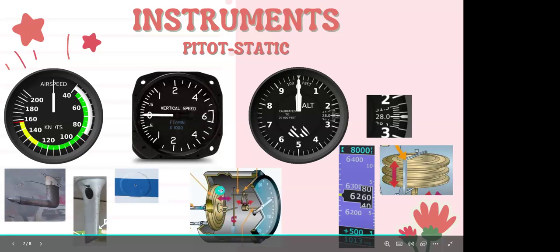Inside of that is what's called a diaphragm. Our dynamic air goes into the diaphragm. Our static air, on the other hand, is fed into the case of the airspeed indicator. That's how they're measured against each other.